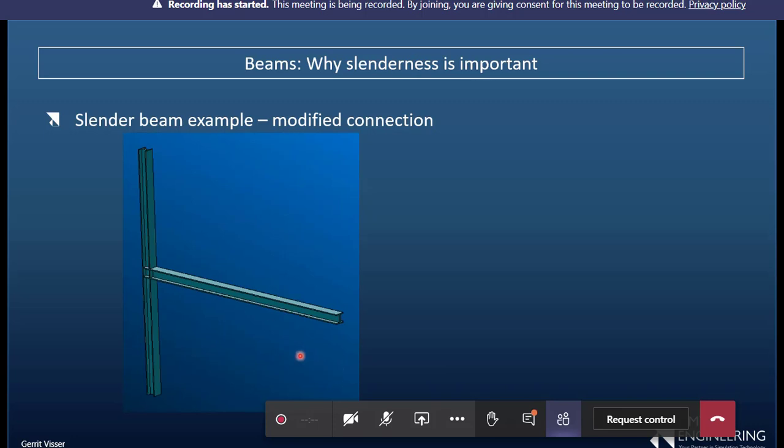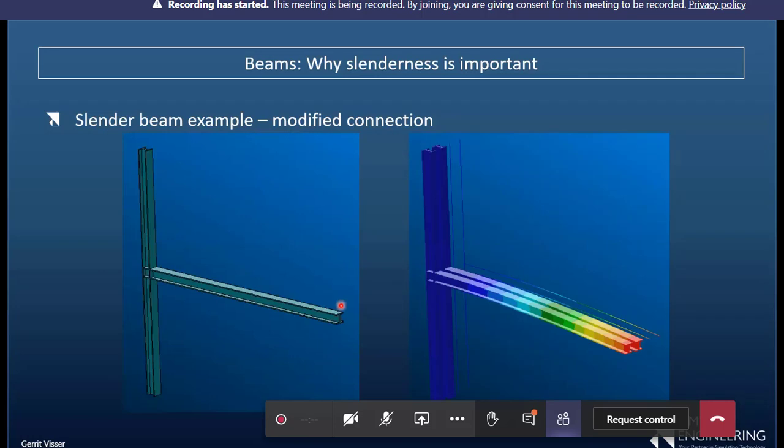So is that quadratic or third power or whatever effect in terms of displacement? And I say different orders simply because it depends on the kind of load that you apply. Whether it's a constant shear load or a tip load or whatever will change exactly what the order of that parabolic shape will be.